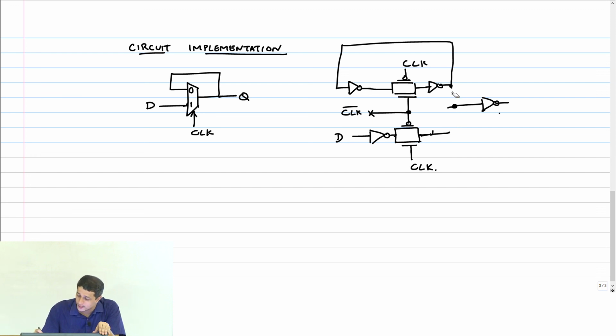No, but again, this cannot be driving here. It has to appear here. Because you can wire-OR only the outputs of a transmission gate. So I cannot connect this to the output of the inverter because that will always be driving something, and I cannot wire-OR something there. So the wired-OR connection should always happen at the output of the transmission gates.